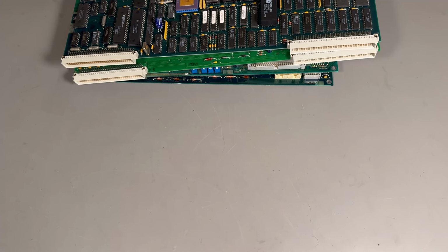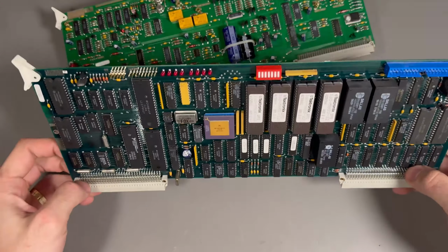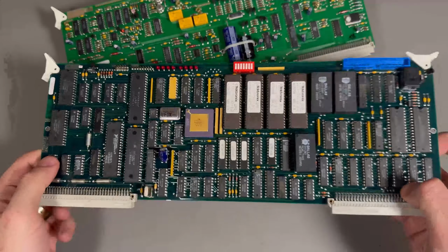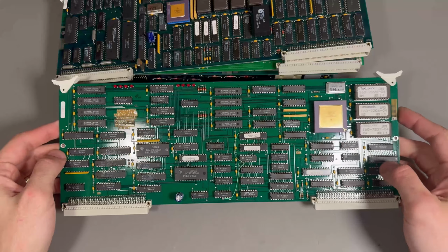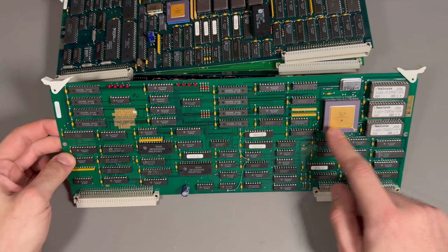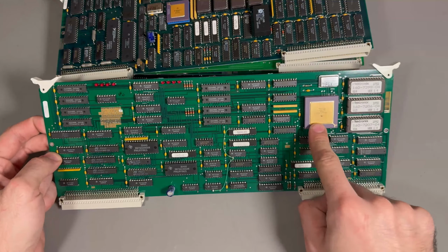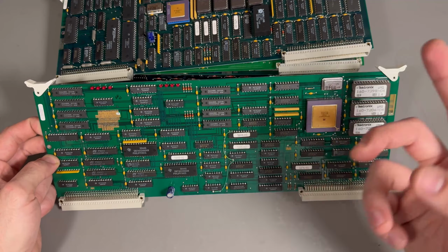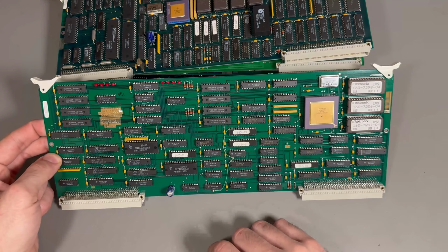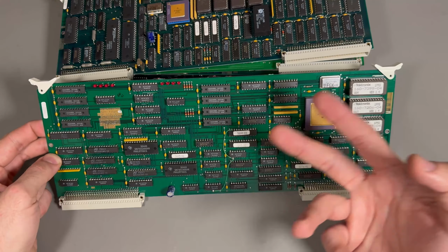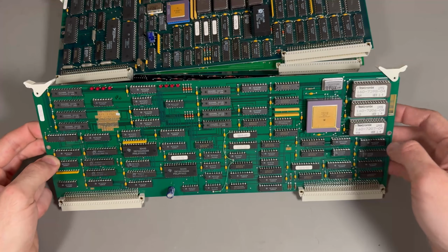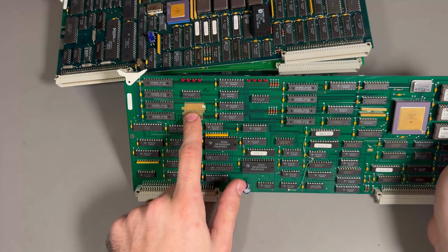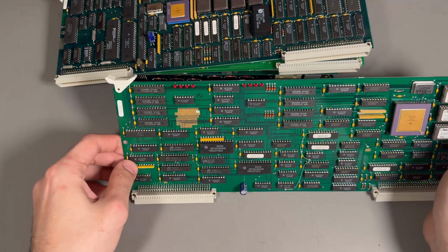Okay, remember I said that doing the centroiding stuff is very processor heavy? Well, a regular SCD5000 would do it with the 68K on here. You could purchase an option for the instrument, which was this. This is the option 1P, I think. This is the centroid. It's a DSP5600, also from Motorola, which does the floating point math and computation required to get the centroids much faster. So instead of 1 waveform update per second, you might get 7 with this. And you can see here it says DSP centroid cage board.